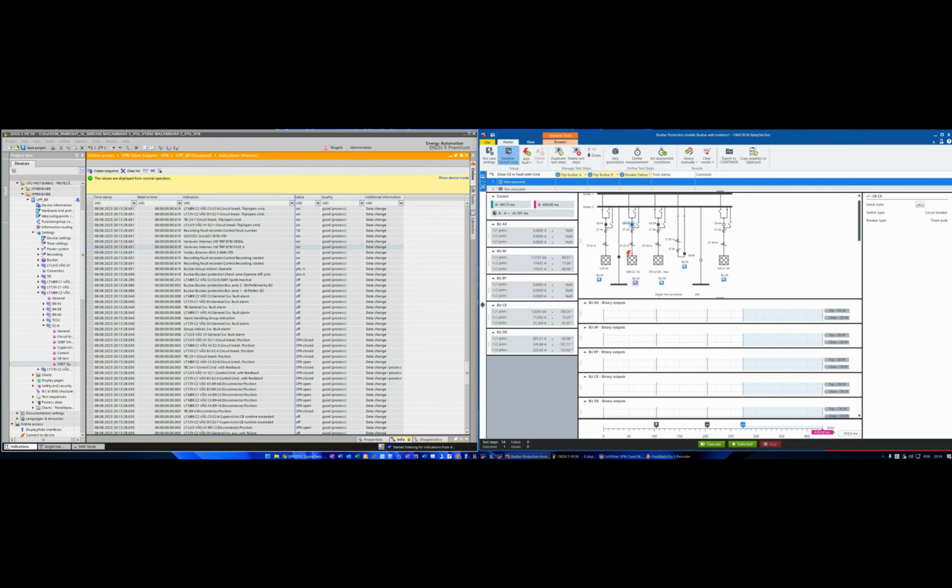And what I have done here is that the contact of my circuit breaker will put the signal in my bus bar protection to one, and I interconnect the signal of the command or the automatic reclose in my bus bar protection. So the circuit breaker is like a command that we can have.